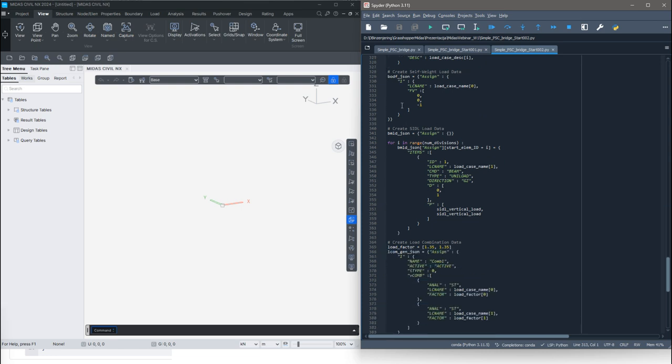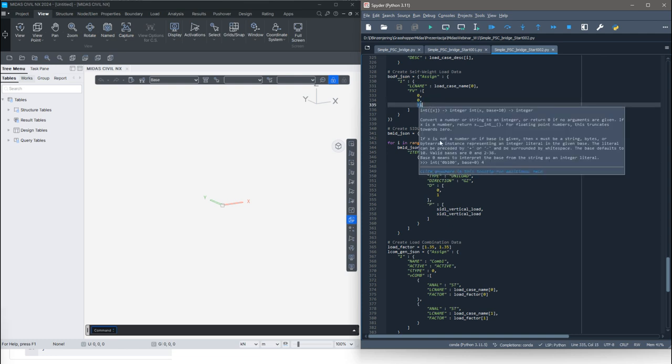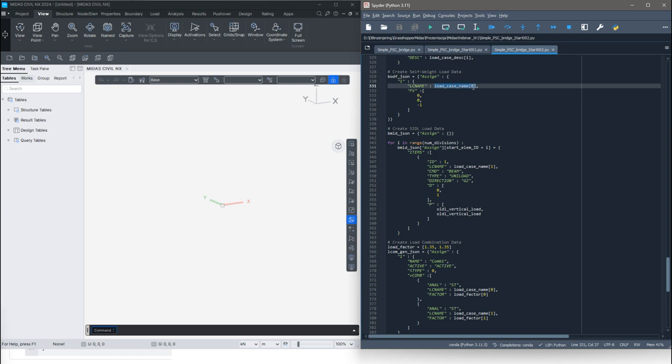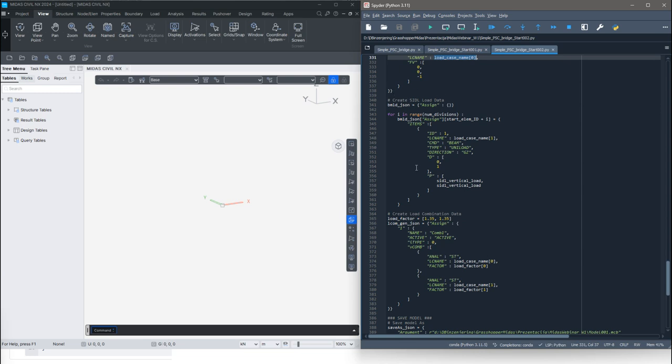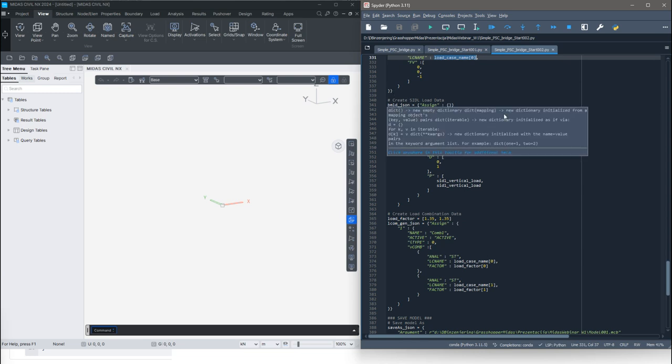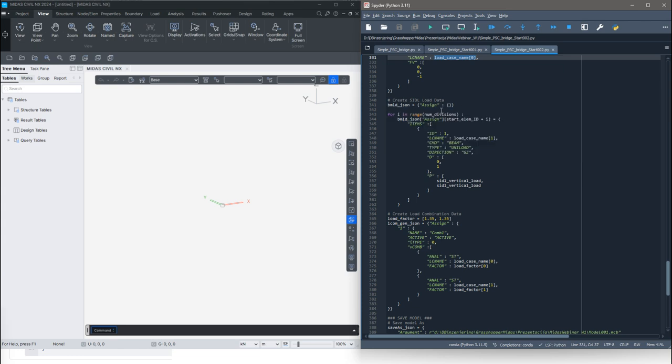Inside this block of code, we prepare body for the command to define self-weight. As you can see here, the -1 is typed for the global Z direction for the load case with the index 0, and that is actually the dead load. In the next block of code, we create body for the superimposed dead loading, that is actually the element loading. As you can see here, it is applied on beams as uniform dead load in the global Z direction, and the magnitude is called here, it calls the parameter defined as -30 kilonewtons per meter.